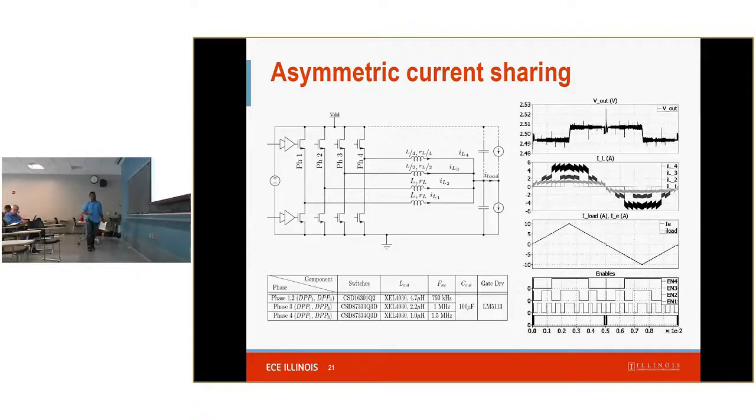This way we can design the converters that have L by 4 inductance to be efficient near that particular operating point, near the 4.5 amp or 5 amp operating point. Then we can design similarly for the 2.5 and 1 amp operating points. So what kind of efficiency curve am I going to get from that?